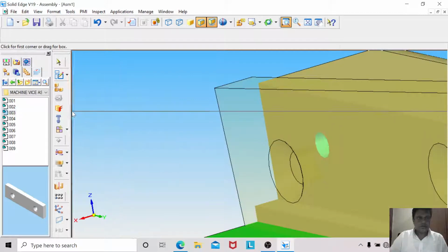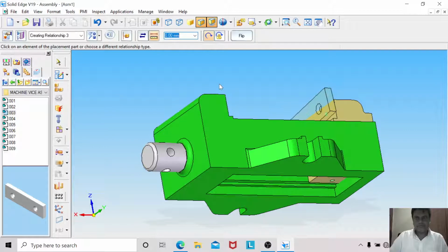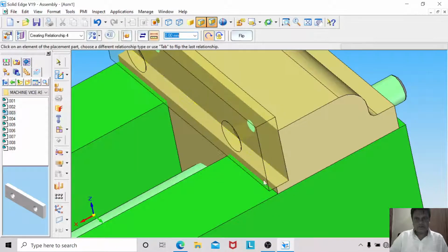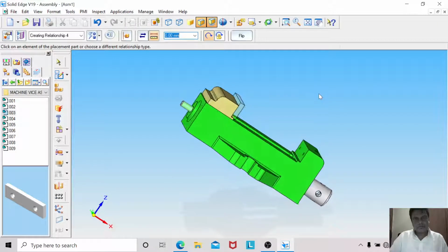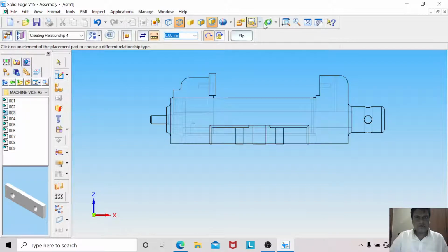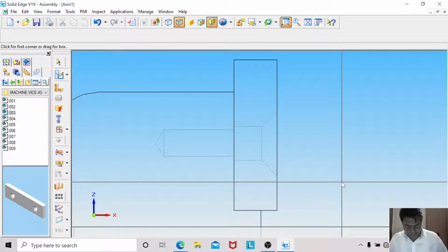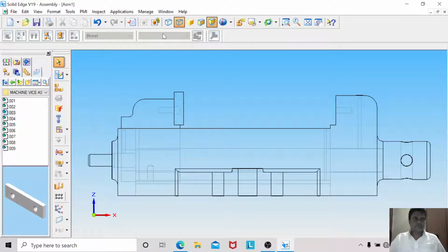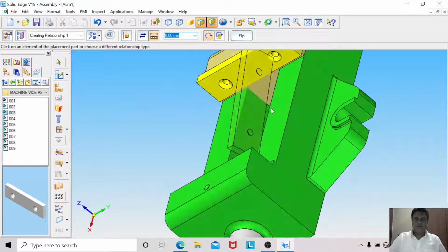You just go to the alignment of this axis to the hole, and then select the bottom face and then select it. Now I think there is no issue with this. They are perfectly fine. Use the wireframe, and make sure that your holes have been arranged on the axis and are collinear or not. Just check it. Okay, it looks fine. And recall this one more jaw grip will come on this face on the body.